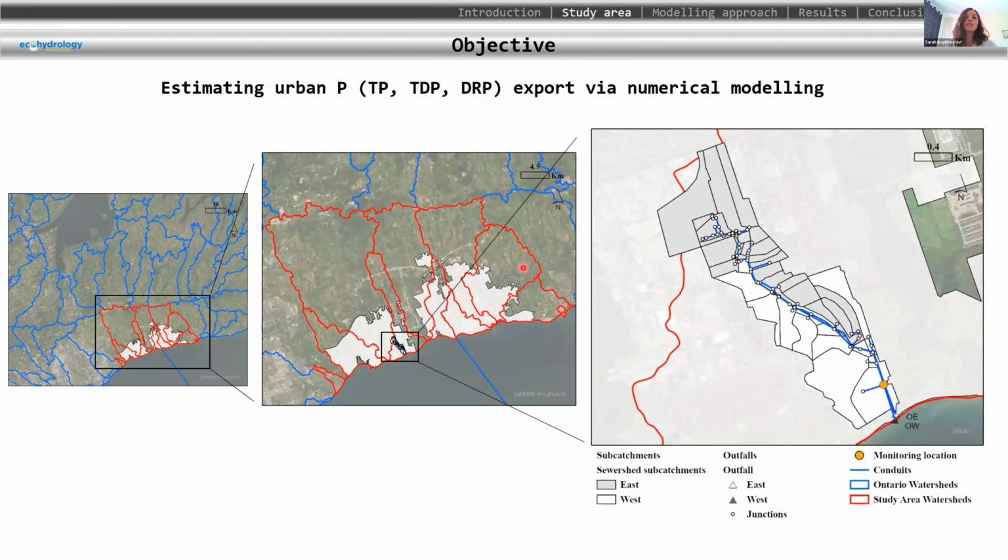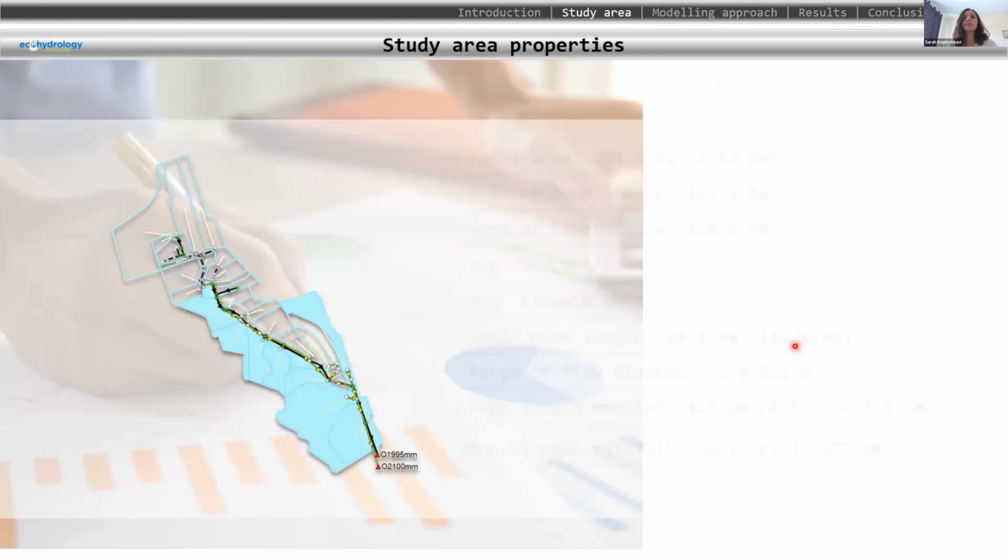So in the long term, we are going to study these four cities shaded in solid white. But today, I'm going to talk about these two watersheds, which one of our presenters, Mahir, talked about before. We have sampled these two watersheds, one shaded in gray, one in white. We had a single monitoring location downstream for each of these, and have sampled for more than 1 year. So we have used these sampling data to calibrate the model.